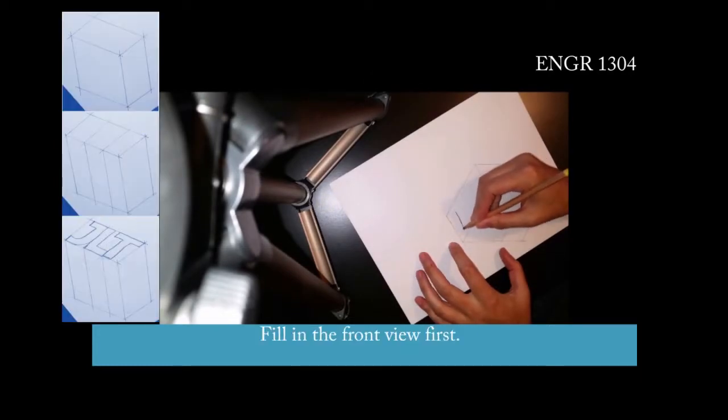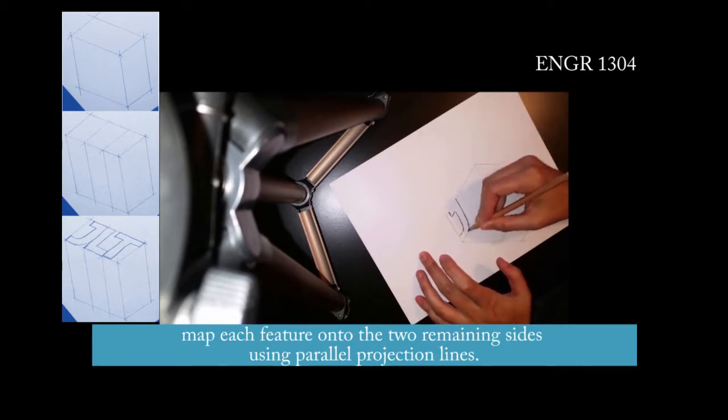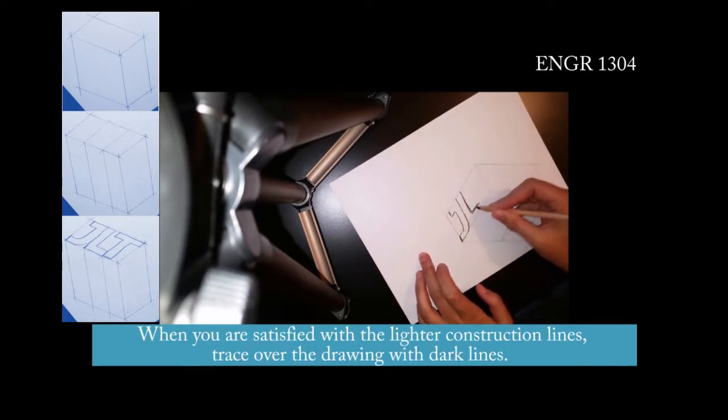Fill in the front view first. Once the front view is complete, map each feature onto the two remaining sides using parallel projection lines. When you are satisfied with the lighter construction lines, trace over the drawing with dark lines.